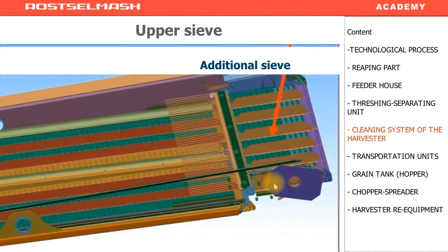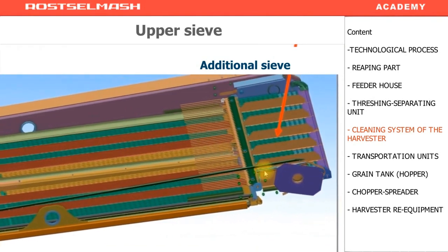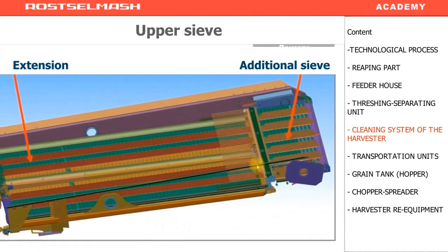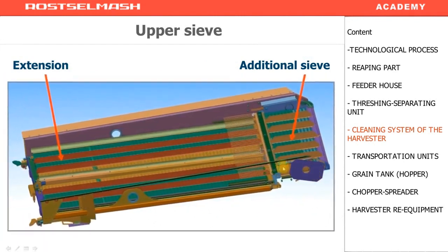In this section, there is airflow. And when the finger rake holds the chaff and straw, the fan blows it all out of the combine. Then the mass is transported onto the upper sieve. While being transported, it is simultaneously spilled onto the lower sieve. And then it moves to the extension of the upper sieve.